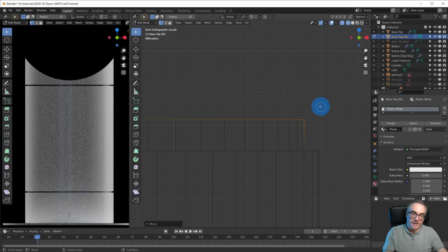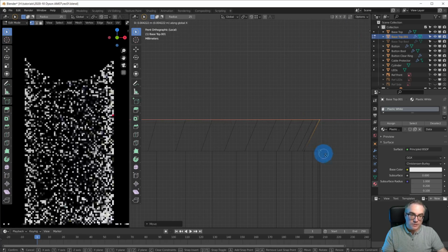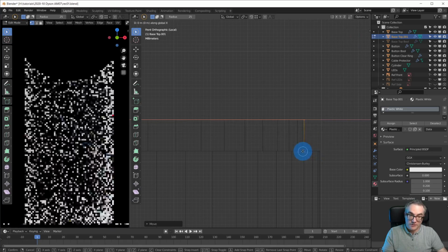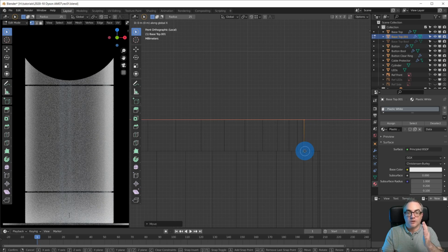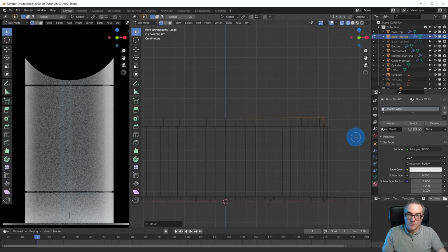If you do, then it does it automatically. But I like to have it off actually. Set to vertices, and then you can go GX, and you can hover over another vertex while holding down Control, and it snaps to that position. And since I'm locking it into moving on the X, it's exactly what I get and what I want.